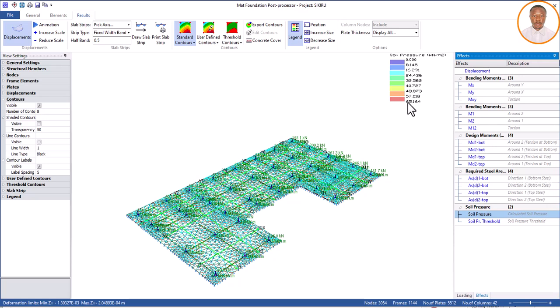Good. So you can now see what we are having here. So you can see that time you discover that this particular load here of this structure was more than what we are getting here. Was more than 67. But now, because we have provided the solution of that toe, which is a cantilever slab that is trying to help us push the soil backward instead of touching the beam, we have now provided that one to push the soil backward. So now the beam is stable. Are we together now? The beam is stable.